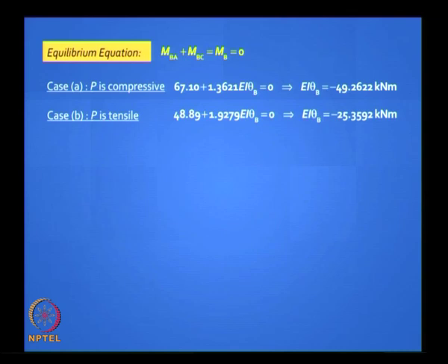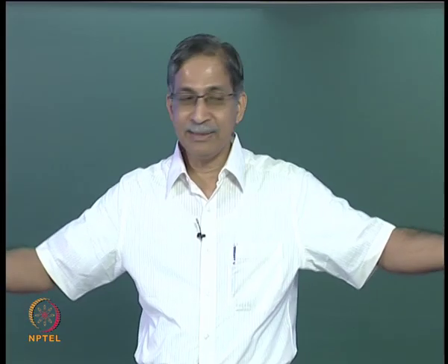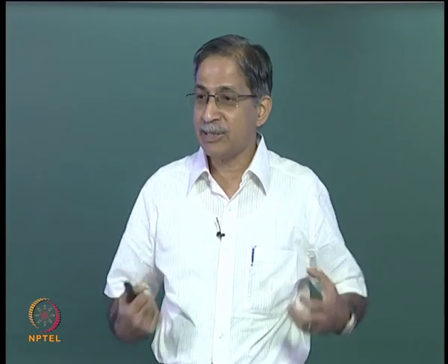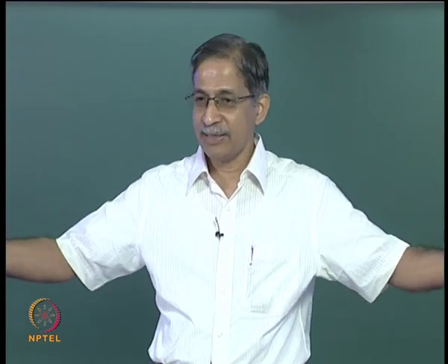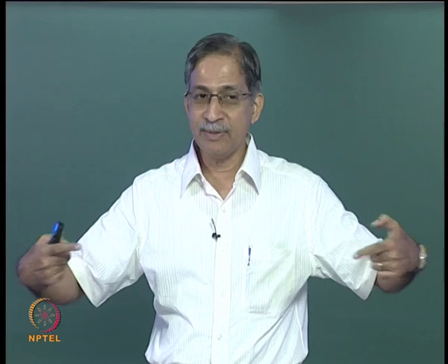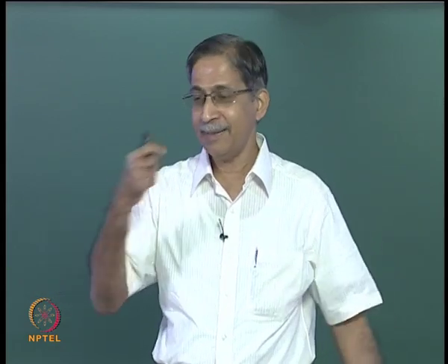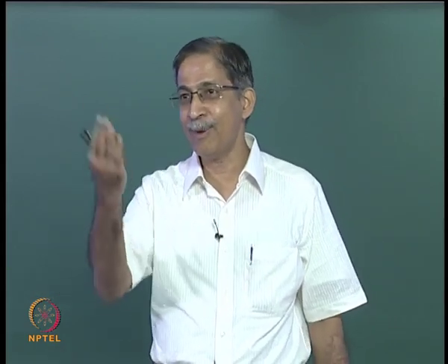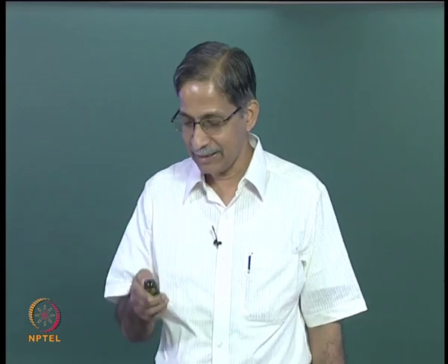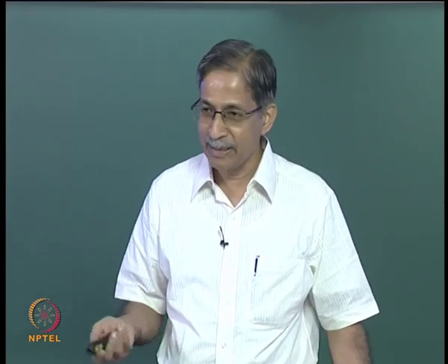When it is tensile, you can feel it, it is going to deflect less, everything will be less. You have a much stiffer structure when you have axial tension, but if it is compressive it makes things worse, and if you did not have tension or compression you will probably get a value in between, exactly midway. Got it? Does it make sense?